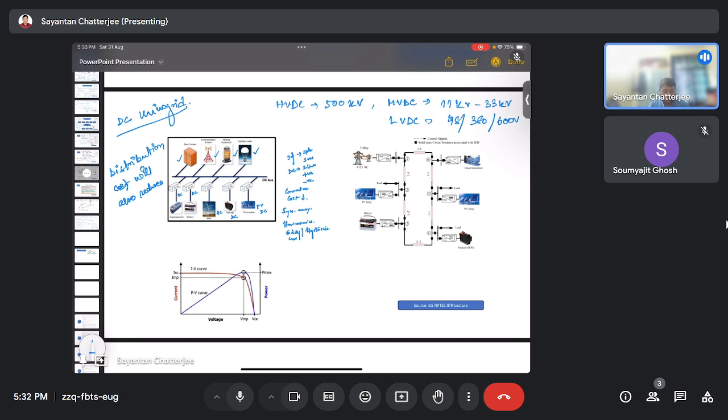So the control actions have become much more flexible as well, and the applications can be done at much lower voltage levels. Also we can see that DC bipolar links can be used. There can be multi-bus topologies framed, a dual bus with which we can separately feed the microgrid. Reconfigurable topologies like the DC ring bus architecture.